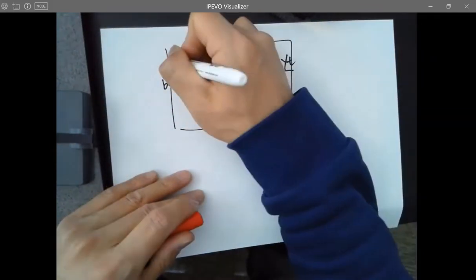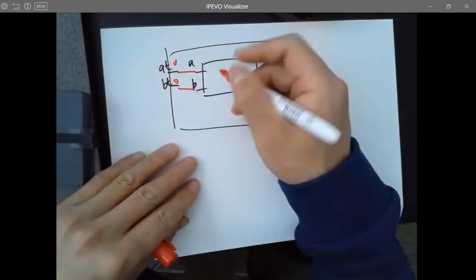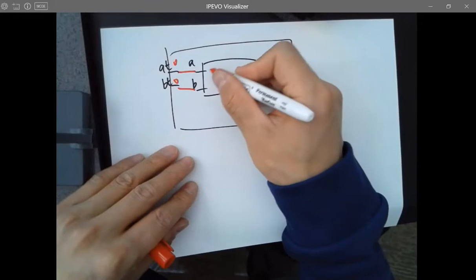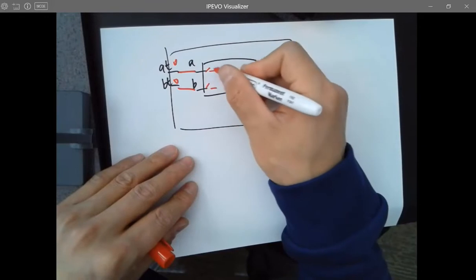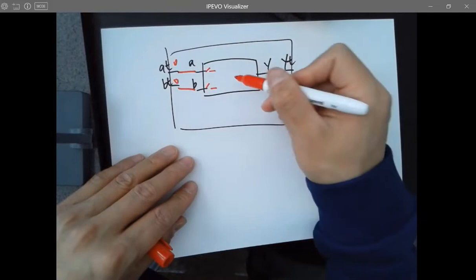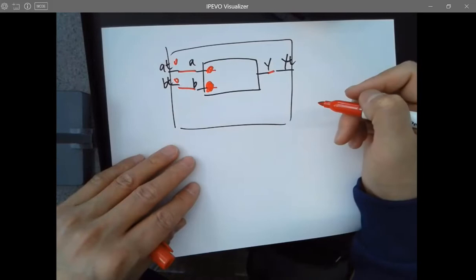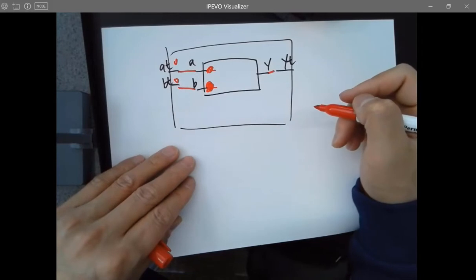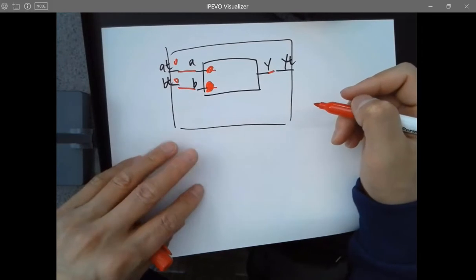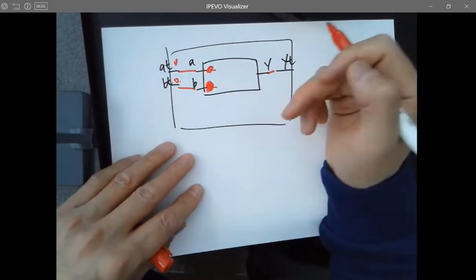So whenever I assign 0, 0 here, what's going to happen? Do you have a switch to turn on and off, just blocking the signal being sent to the sub module? You don't. They are connected. That's it. It's a combinational logic. You don't need to wait for any clocks. Whenever these values are here, there will be a little time delay, but in the simulation, it's ignored.